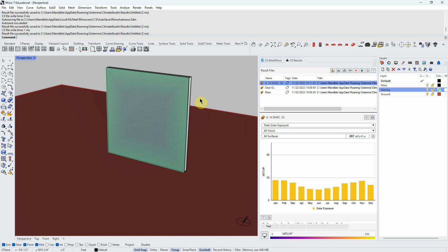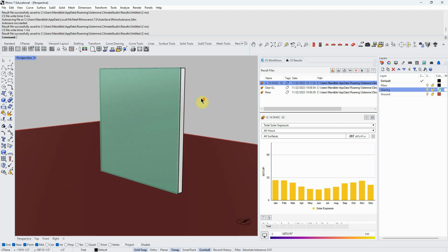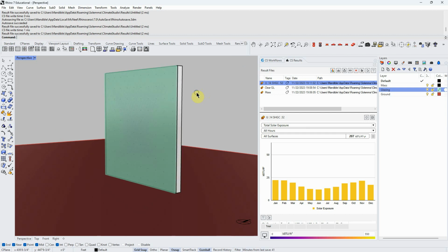And then we could use that to offset some portion of the site EUI. It may not be very much. It may be decent. I don't know, you'd have to check and see. But I do think this is a reasonable way, with the tools we have, of simulating a Trombe wall. Not at all saying you need to do it or should do it. I just wanted to answer the question. I thought it was interesting. It's going to be on my list to find a more accurate way of doing this moving forward with some other program, probably.